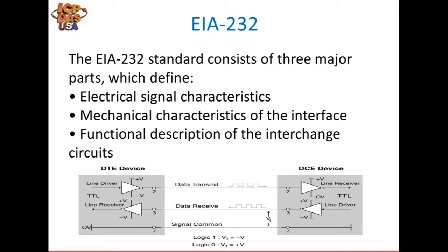For shorter distances, however, transmission rates of 38400, 57600, and 115200 can also be used. Based on field tests, it can be shown that much longer cable lengths are possible at lower baud rates. Note that the achievable speed depends on the transmission voltage and cable capacitance, as well as noise in the environment.